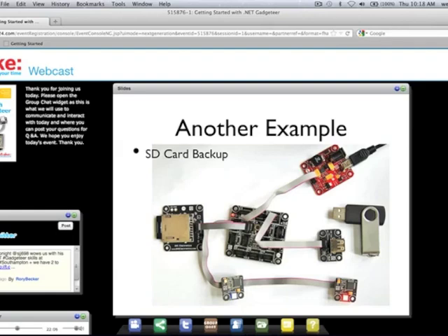So there are two storage interfaces connected to the main board. The one on the left is for an SD card, and the one hanging off the right of it is a USB host socket. Also hanging off the main board are two LED modules. You can see that one is kind of lit, well, I'm not sure it's lit at all actually, but the one on the right is red. Only one of these LED modules is actually connected directly to the Gadgeteer main board. The other one is daisy-chained off the first one. So you can actually create strings of these multicolour LEDs all joined up.